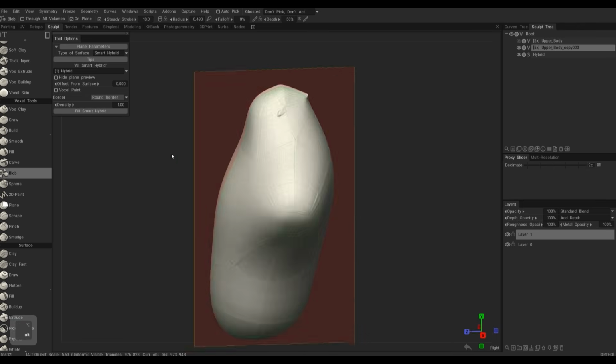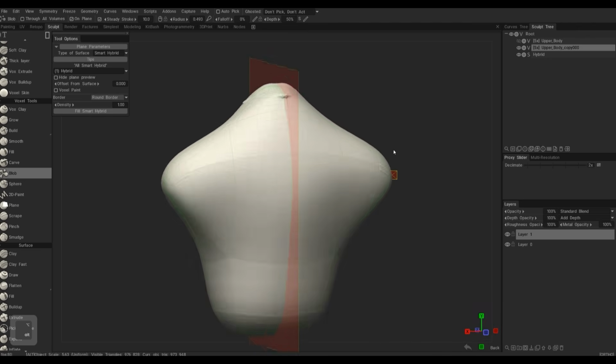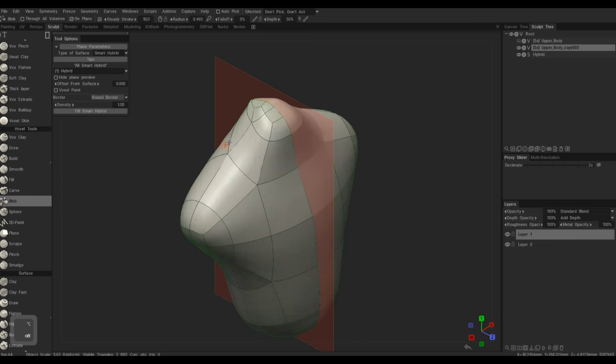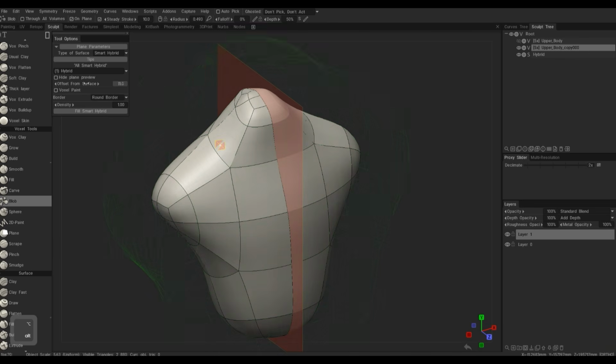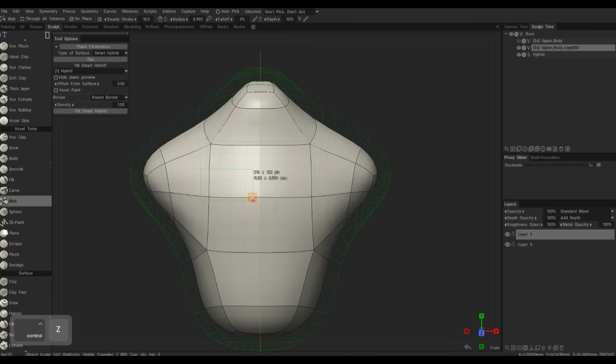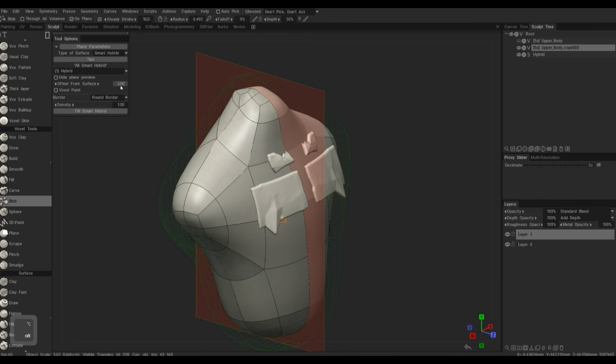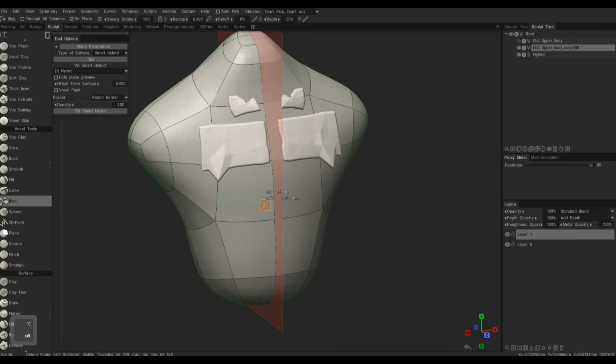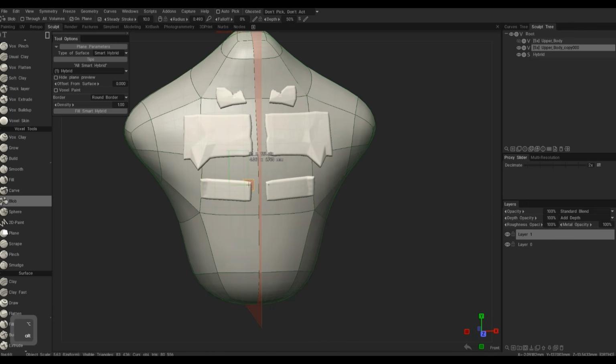So then we get a surface, a voxel-filled thin surface. If I undo it, we can go back and there are these options here. I can offset it. For example, since this surface is kind of sinking into the existing sculpt too much, I can do an offset and I can start creating shapes with an offset. And I need to rotate and face my camera with my projection. I usually don't use offset. I try to clean to the surface because it creates fewer issues and I prefer it that way.